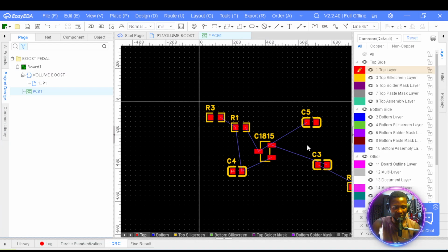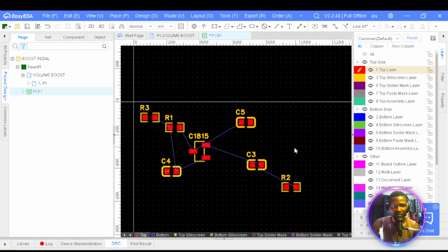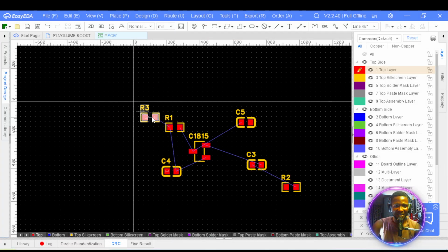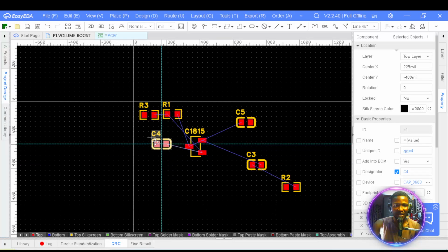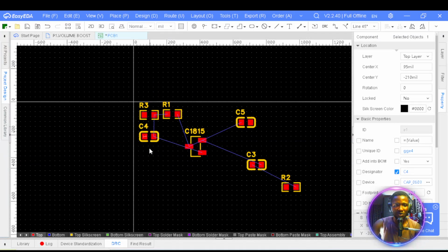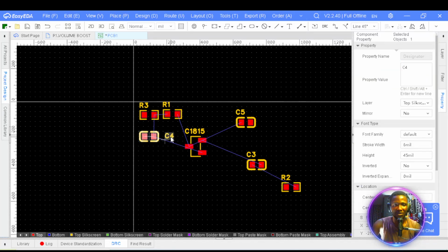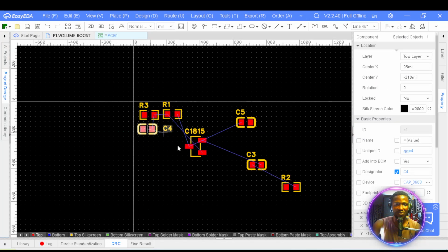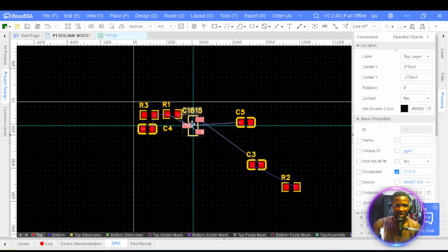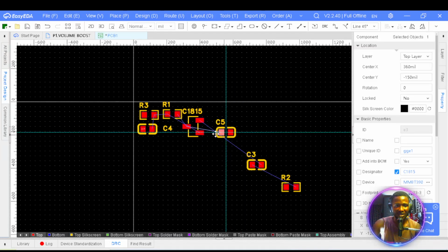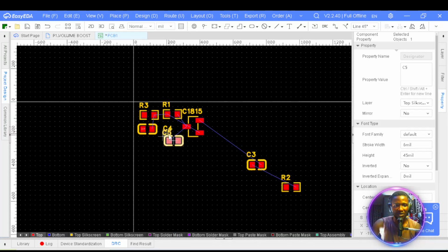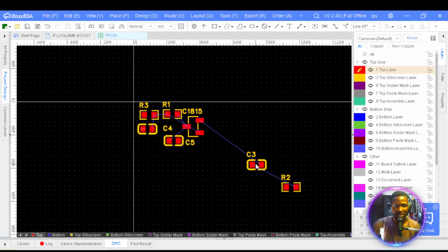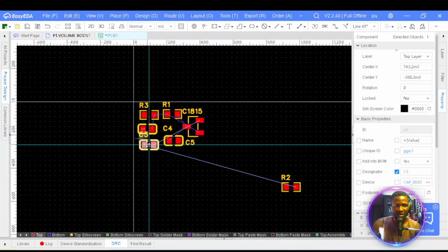Alright, so let's go now. So this is what our PCB looks like. Don't worry, I know it's still boring. So put this one here. You can now arrange it the way you want. And in the process of arranging it, it's good you understand the way some of these components work. Like for example, transistors by default get hot, so you want to give them space so that they will not affect other components. So put that into consideration. It's not just about managing space alone. No, consider the nature of those components.